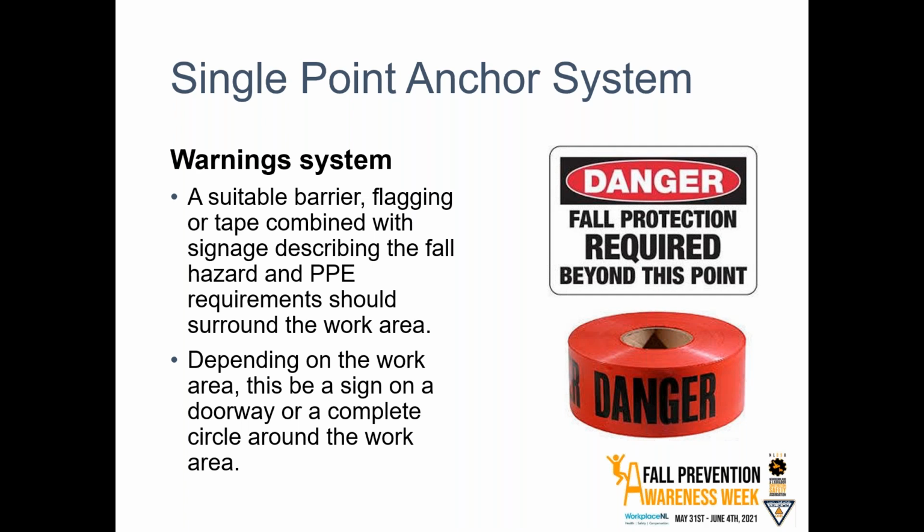But if you're using soft barriers, and what I mean by soft barriers are things like flagging and danger tape, it's really important to keep in mind that these types of warning systems are visual systems, and they're not actually going to stop anyone physically from falling into an opening. They're there just to warn, and for that reason, it's a good idea to set them up at a distance from, say, an edge, so that people have the ability to see it, recognize there's an issue, and again, they're not right on top of that hazard.